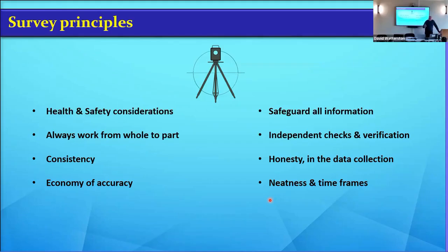But you know, I had a lady, and she was quite old. So we were doing the leveling, and she was leveling all the points, and I was telling her how to mark up the sheet, put the level number on it, put it on your sheet, and then when you get to the office, you process it, and then you can add it to the drawing. And I said, you can use the staff back and forward, and you read the lowest reading, or you can use a level bubble and put the level bubble on the side of the staff.